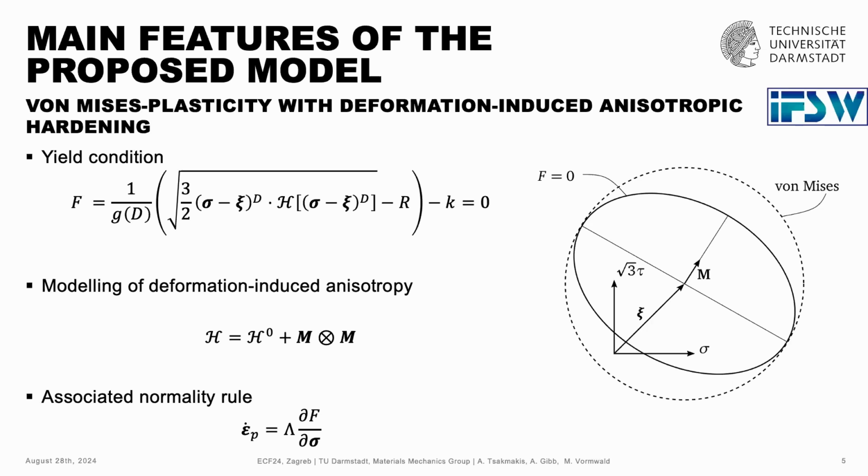So essentially, we have not yet implemented this model in conjunction with the phase field approach, which is why, for the sake of this talk, I will confine myself to the classical von Mises hypothesis with kinematic and isotropic hardening only. Nevertheless, in terms of the understanding of how this phase field model is working, we will get exactly the same insights. It's more of a quantitative difference.